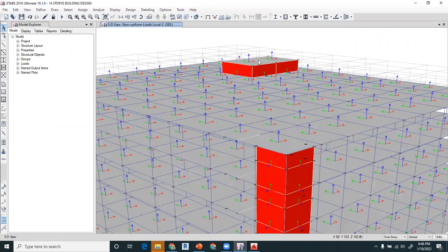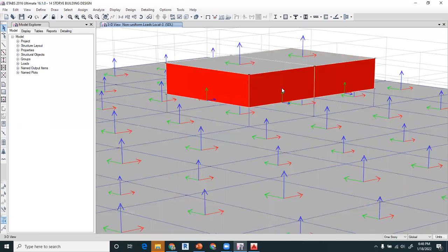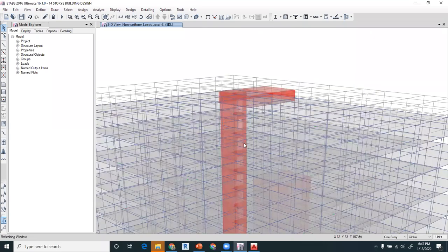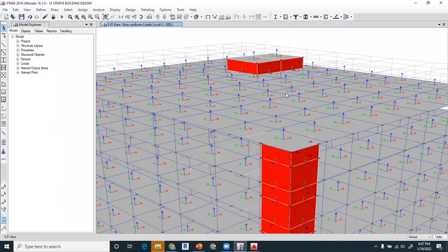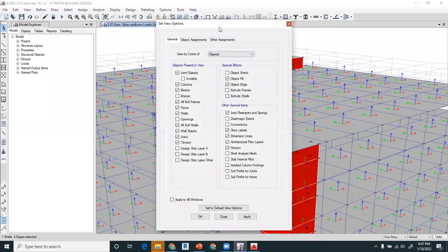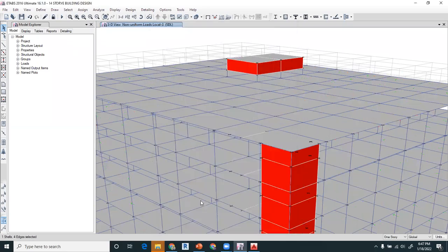in the lateral direction, these will be the live loads. So when you apply the live load, the live load also contributes to the seismic forces. So it will produce tension in your columns. You can do your case studies on that. So there will be tension in your column, because columns are normally designed as compression members. So when there is tension in your section, it will be shown as a failed section, right?